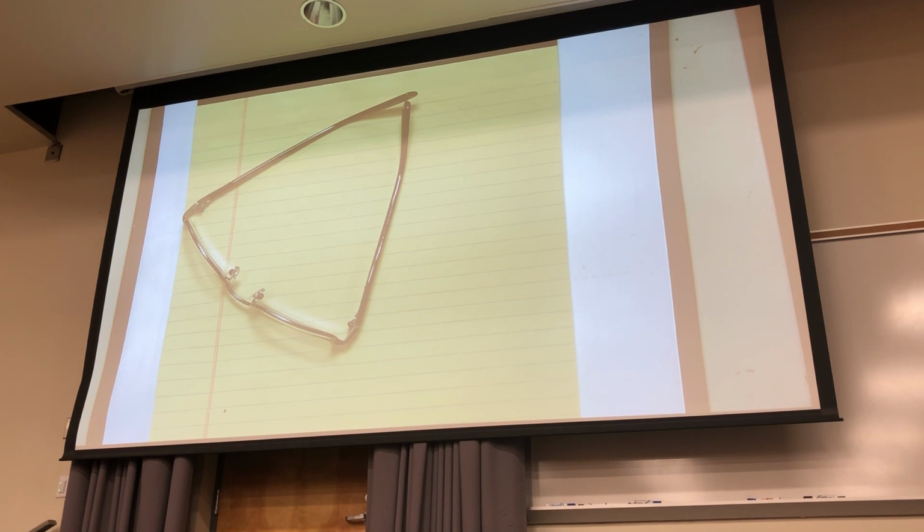So here's what I'm going to do. I'm going to start with the Laplace transform, which you know pretty well, right? Remember, this is analysis, not synthesis. I'm going to take the Laplace transform and take a sampled signal. And then I'm going to get something akin to the DTFT, which will be called a Z-transform. Only it will not be in the j omega sample domain, it'll be in really the S domain, which has a real and complex value to it. Follow me on this? And then we'll see this is the real tool that we use, like we do the Laplace transform for both analysis and really synthesis. The analysis you can do with the DTFT, but synthesizing things you need the Z-transform. So that's where I'm going.